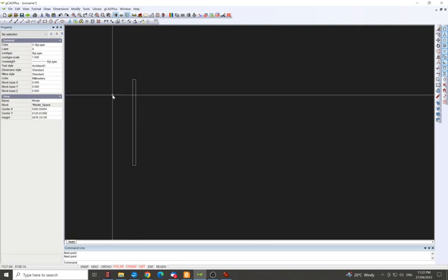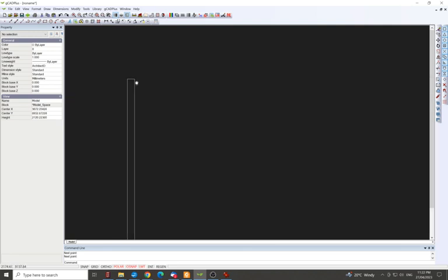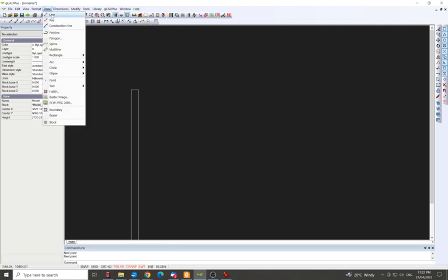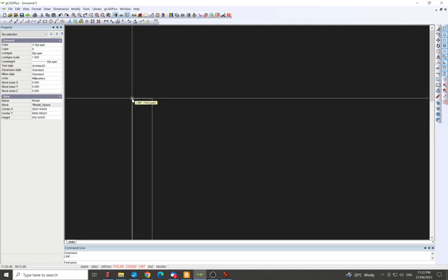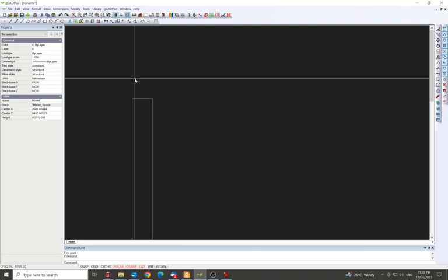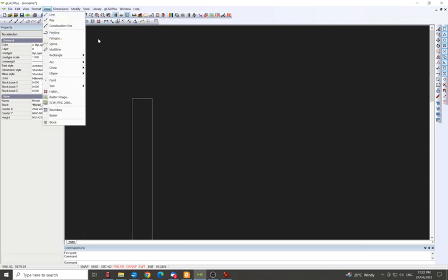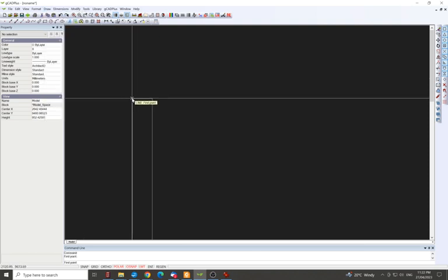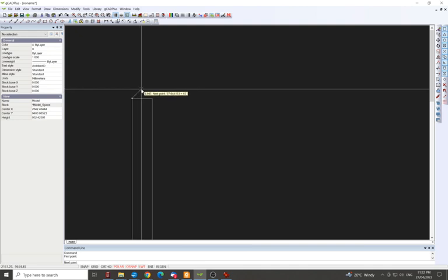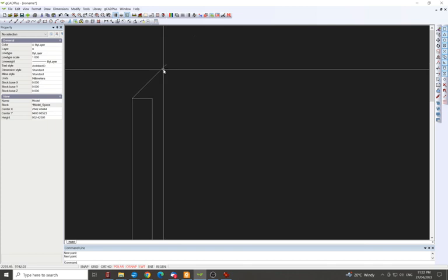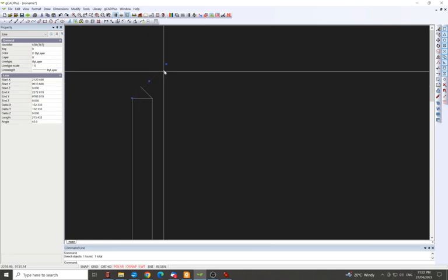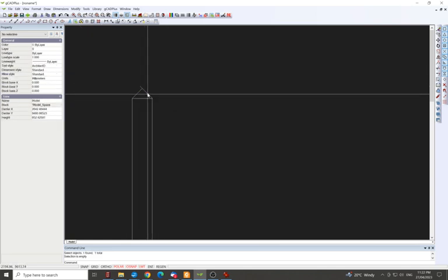So the next thing we want to know is the total. Well, actually what we'll do first, we'll just draw, because we've got little caps on the ends of these. One way I'm doing things and not explaining them. One way to do it is instead of going draw a line each time, you go line, click there. We want 45 degrees. I'm just going to manually do it. Click it out where it's 45 there, and then I'll get another one on this side from that way, like that. And you can bring these in like that, but there is a way to trim them too.